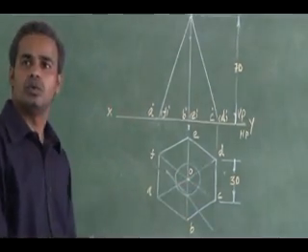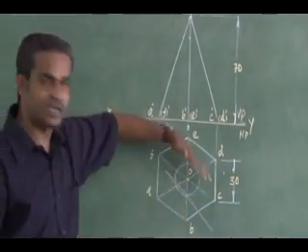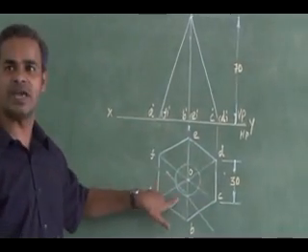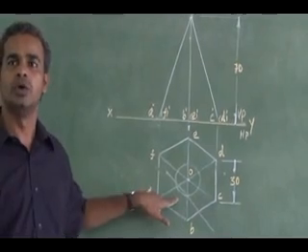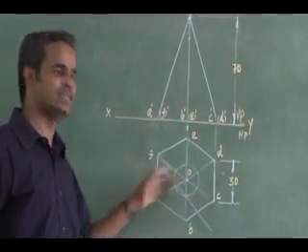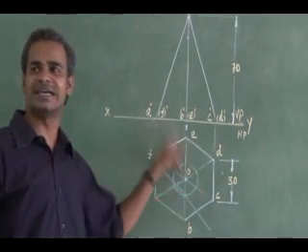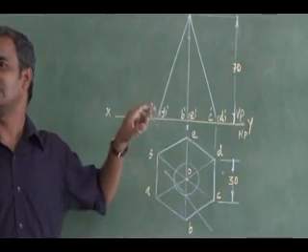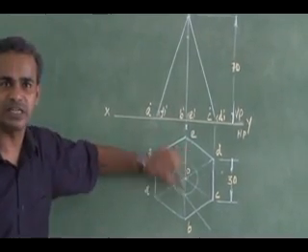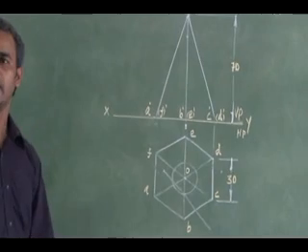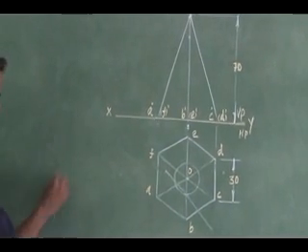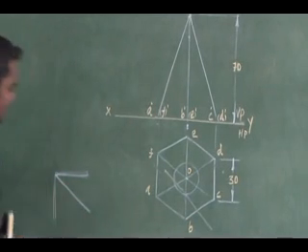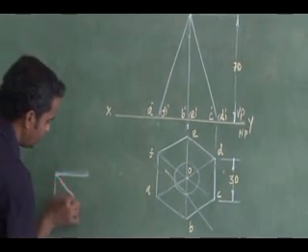So what exactly does 10 mm away mean? From the axis, the cutting plane has to pass tangent to this circle, tangentially 10 mm away. So I have to draw a construction circle, measuring 10 mm radius from the axis. Then you can tilt your drafter to 40 degree.